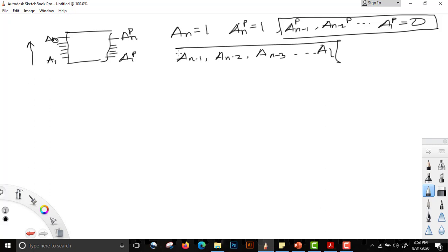That is, the highest priority belongs to AN. If AN is equal to 1, then ANP will be 1 irrespective of what other inputs are, and all the other outputs will be turned into 0.